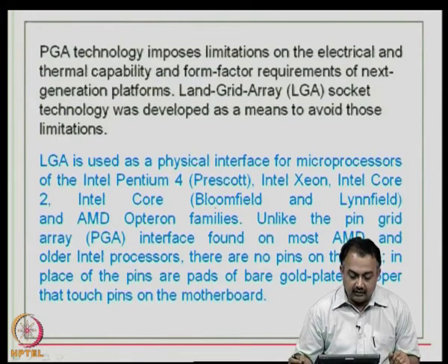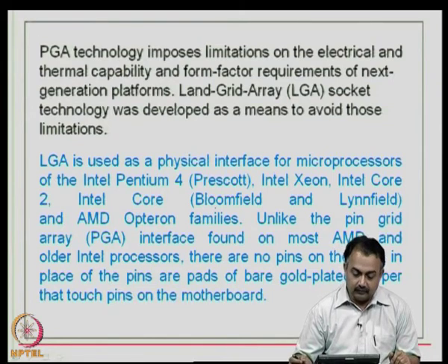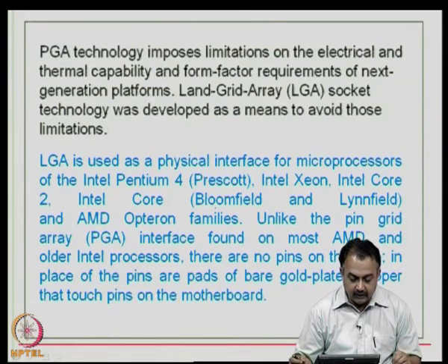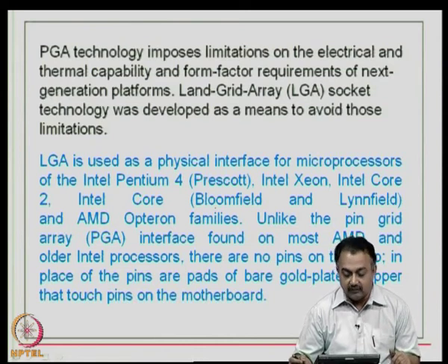LGA socket technology was developed to avoid all the problems that were encountered with BGA, okay? Especially in terms of larger pad area, contact area and so on. So, LGA is used as a physical interface for microprocessors of the Intel Pentium 4 family, Intel Xeon, Intel Core Duo processor, AMD Opteron families of microprocessors and so on.